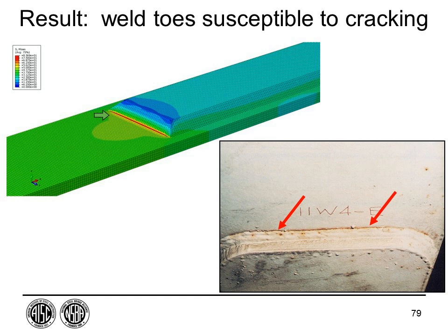And what we also use, and this is in AASHTO, is what's called single lane ADTT. In other words, what is it in that one lane? Because remember, the fatigue truck is assumed to be one truck in one lane. If the ADTT is spread across lanes, like 30% in one lane and 70% in another, you need to take that into account. So rather than having the actual ADTT number, how they give it to you, it's more important to know, is it bidirectional and is it per lane, and that kind of information when you're doing an